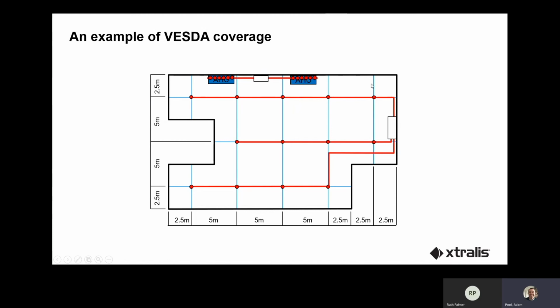And it's also important to point out from a design perspective, when we're looking at design of aspirating, you've got to consider the capability of the system. So is the detector capable of having this number of sampling holes connected to it and still achieving the sensitivity requirements for a Class A application? So that's down to the design of the system and the product chosen to be used.